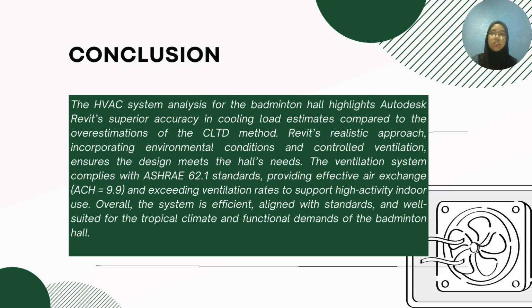The ventilation system we analyzed aligns with the ASHRAE 62.1 standard, ensuring optimal air exchange and air quality for high activity indoor environments. Overall, the proposed HVAC design meets the functional demand of the badminton hall while maintaining energy efficiency and suitability for a tropical climate.